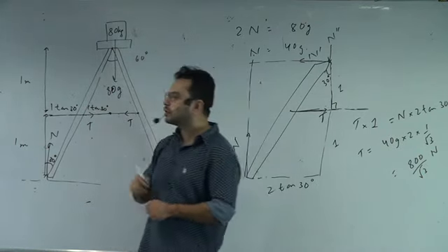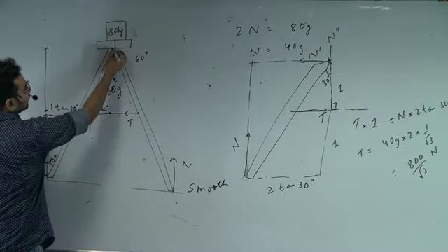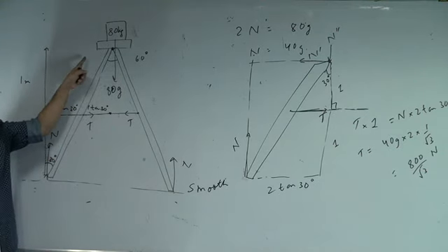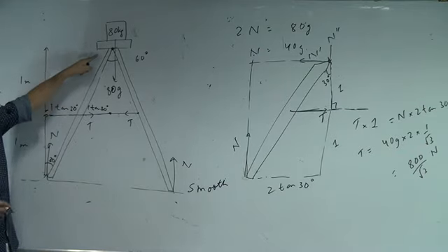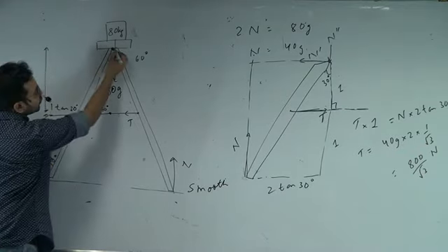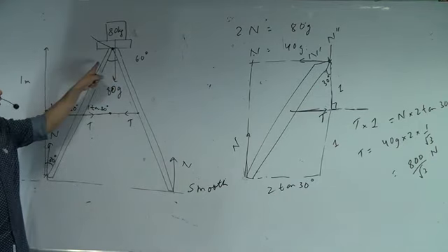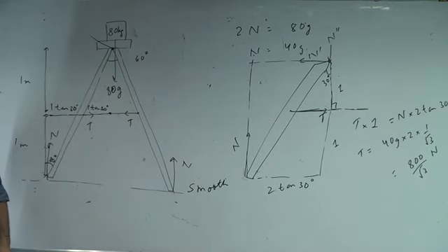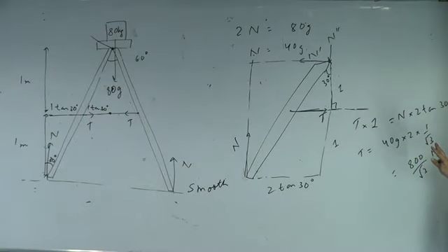नहीं, but you're going to miss one force. Which force are you talking about? यहाँ का force. So you are telling me कि this leg का equilibrium we are talking about, right? We can write the equation of translational equilibrium of this leg, right? Then there would be a force from here, no? The force exerted by this leg on this leg, that you're going to miss. Is that clear? Now is this clear to everyone?